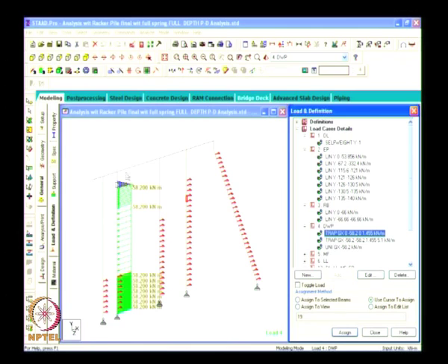Then we have the differential water pressure. Differential water pressure means on this side of the sea the water level will go up and down, and this going up and down will be based on the tidal range. Here we put what is known as a good drainage condition. So whenever the high tide water comes it goes inside, and there is groundwater due to rain that also comes here, but when this water goes down, this water does not go down in the same phase. That means this will go faster and this will go slower, so this acts like a water tank and you will have some differential water pressure.